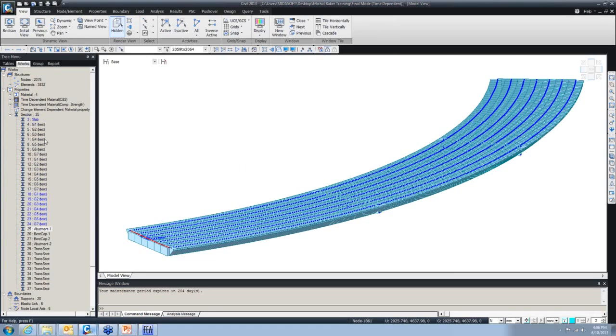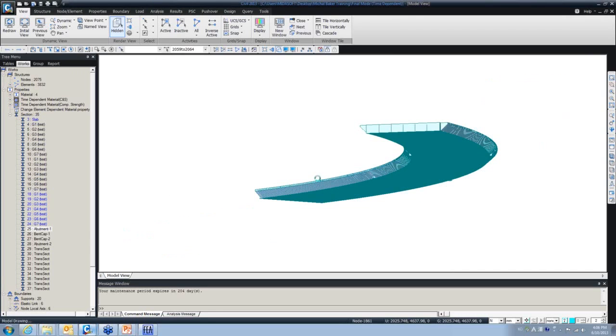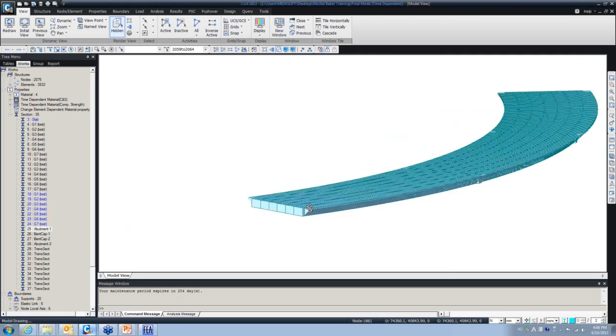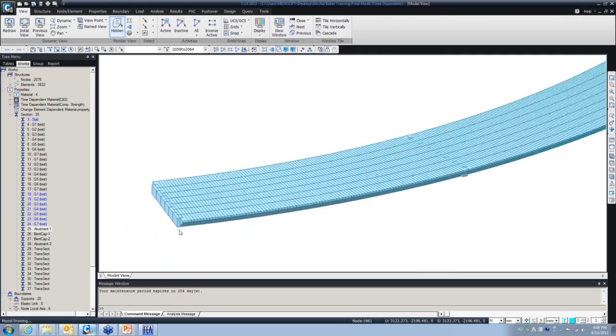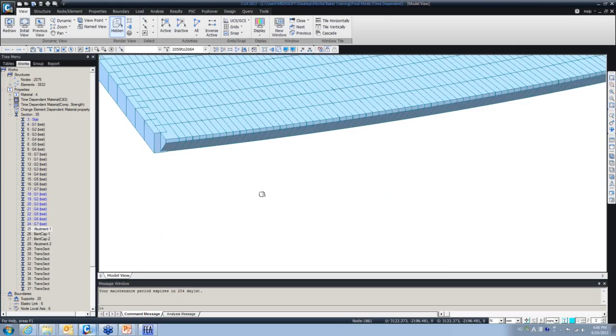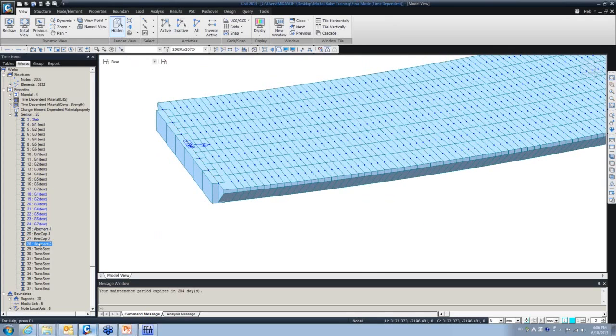Joe asked a question: what does the grillage wizard use for transfer links? Actually, the transfers are not links; they are elements. So let me show you. For example, for these elements right here, it automatically considers those connections with the small beam elements. So that's what the software automatically does. So you don't need to be worried about that. But if you want to change them, you can simply change it from here.